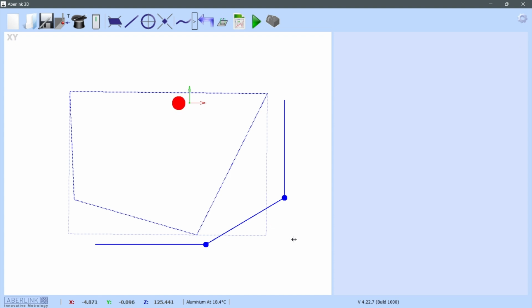It's going to be 2 separate dimensions, so we'll click on this point and click on this point, and then again I can move it to the left hand side and that automatically aligns in Y, or if I move it up to the top it automatically aligns in X. So sit it wherever you want. I'll sit this one down here.